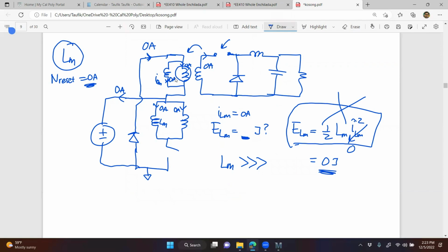Sorry, could I ask, in class you talked about how this circuit is one of the reasons we know Lm exists, right? Exactly, because otherwise there shouldn't be current flowing through that winding. The only reason why there's current present in the circuit has to do with the magnetizing inductance. That's correct. So let me change this, okay? This has nothing to do with this problem.